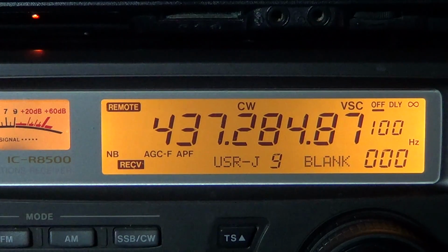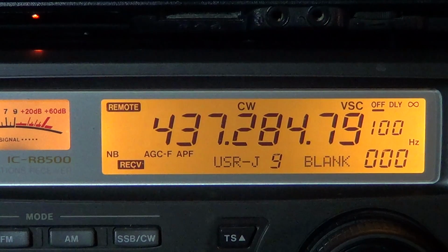The digital transmission is an AFSK 1200 baud on 437.400, plus or minus the Doppler shift, of course. But the main frequency for the downlink of the CW beacon, you can see here, this is the main frequency. This is what we call the center frequency, the original frequency at which the satellite transmits. And this is the adjusted frequency for the Doppler.